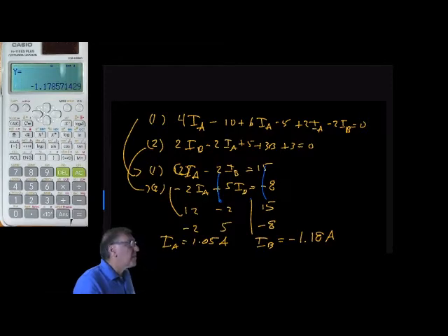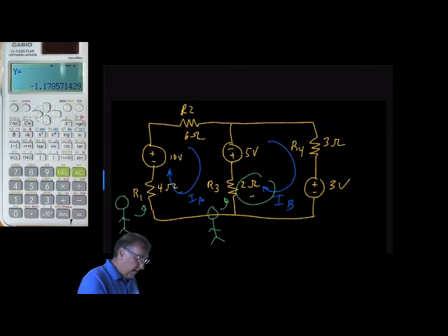So again, some advice here, as we mentioned before, always show the currents going in a clockwise direction, and also start at the lower left-hand side of the circuit as you traverse around each loop, here and here. It'll be very helpful in calculating these circuits.